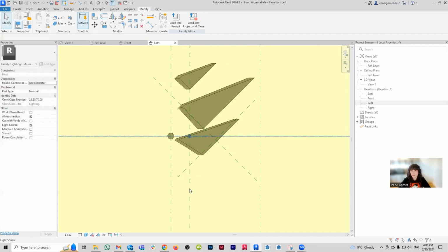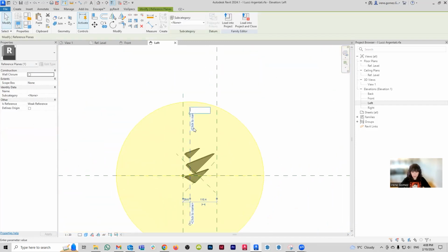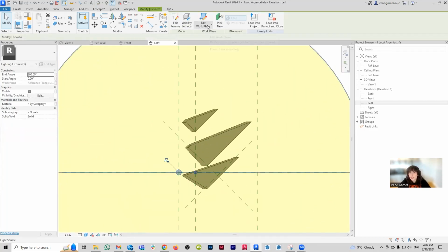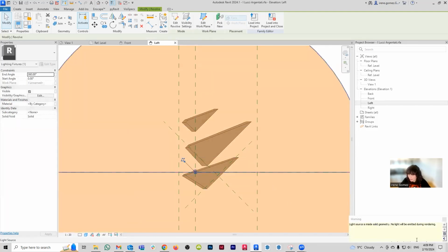I'm going to need to name this guy. There we go. Let's call this guy light. And let's see if I can just pick a new host for this guy. If I edit my work plane, pick a plane, and I'm going to pick this guy. Yes. Now, don't panic about the message that you're getting.